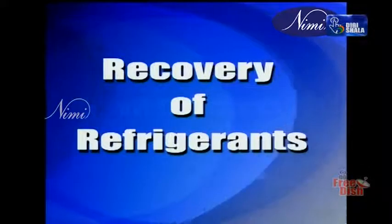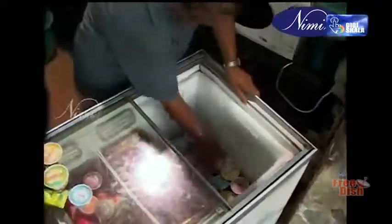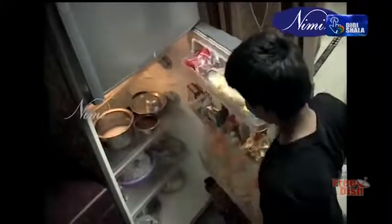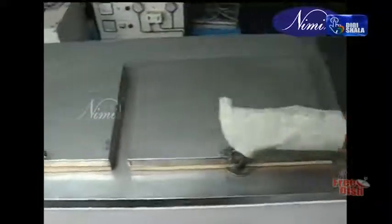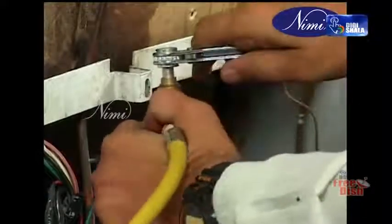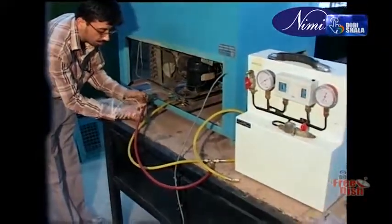Recovery of refrigerants. Recovery of CFCs and HCFCs refrigerant from deep freezers and refrigerators is necessary for the cause of ODP and GWP. In case of faulty deep freezers, we have to recover R12 refrigerant in a separate cylinder. For this purpose, a separate recovery unit is required as shown.